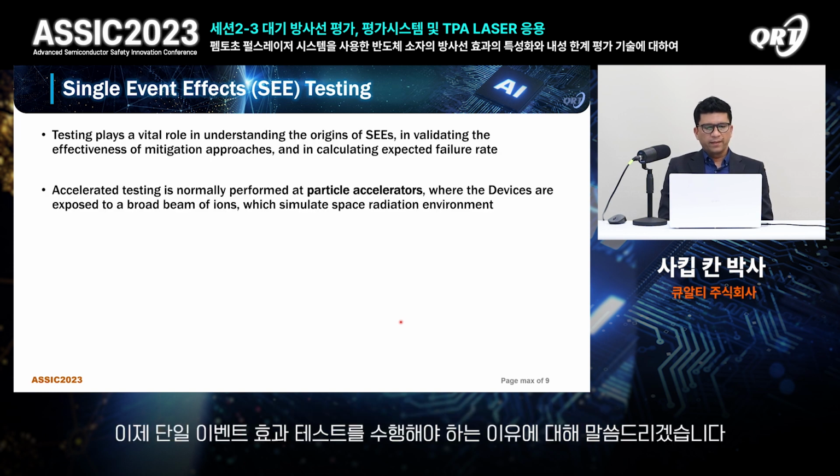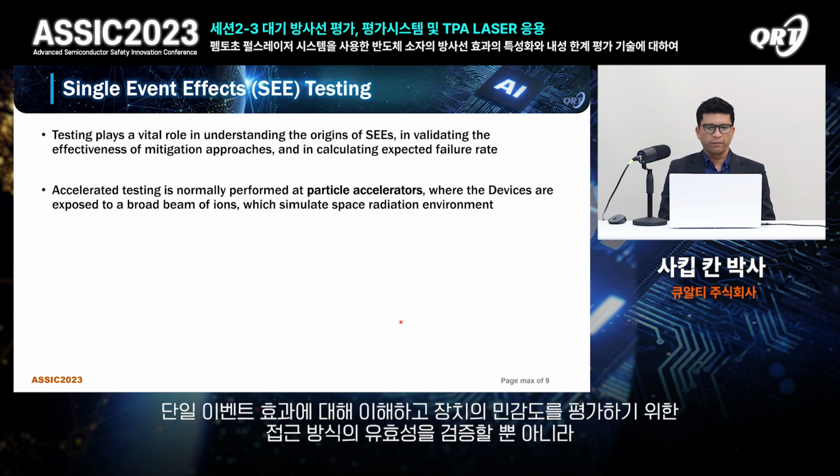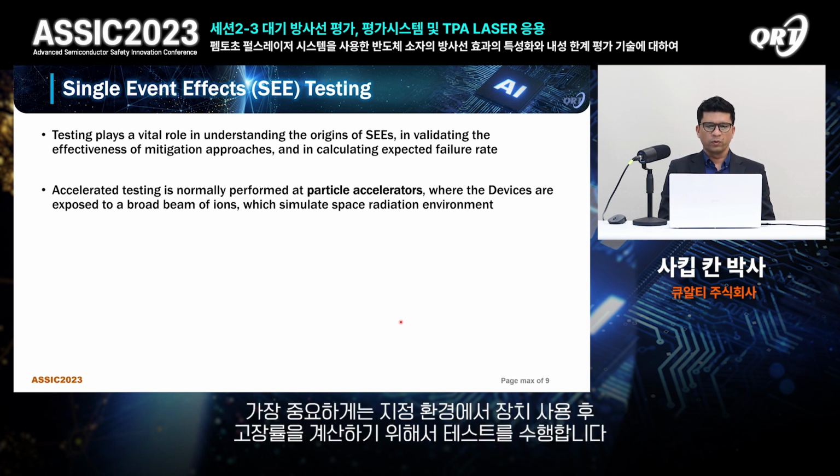Now let's discuss why we need to perform the single event effect testing. Testing plays a very vital role in understanding the origin of the single event effect, in validating the effectiveness of the mitigation approaches, to evaluate the sensitivity of the device, as well as, most importantly, to calculate the expected failure rate of the device in the given environment.